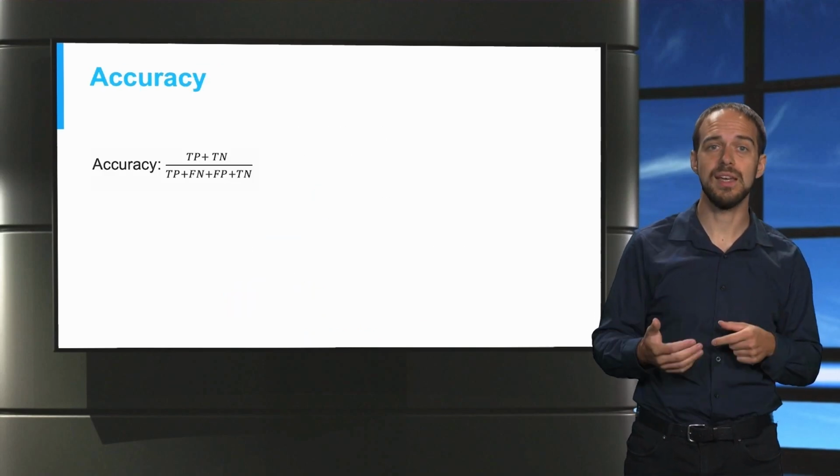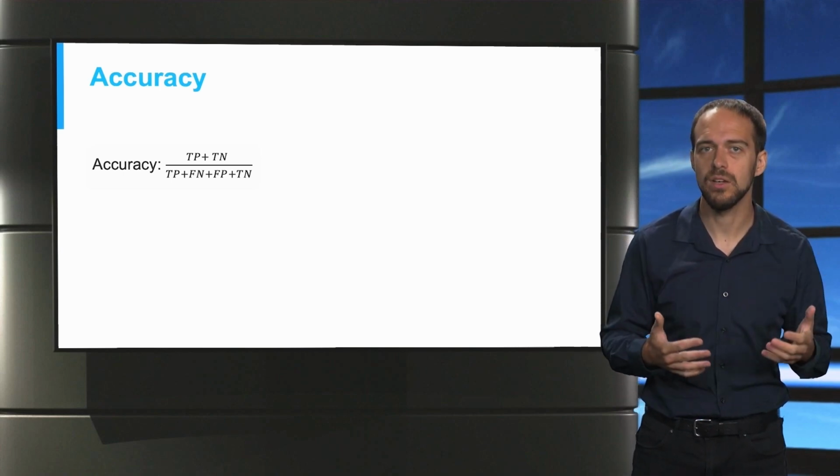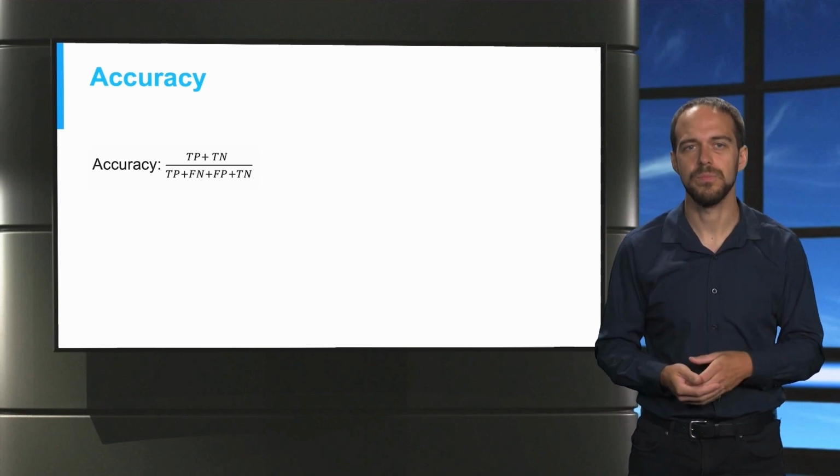Accuracy, specifically for DSA, is a significant subject. The accuracy is the correctly predicted operating conditions divided by the total number of conditions. However, sometimes it is worse to predict one class more inaccurate than the other. For instance, in DSA, to miss an alarm for insecurity is significantly worse than having a false alarm. For false alarms, we perform further analysis and place preventive control actions, but a missed alarm could lead to a total power blackout of the system.